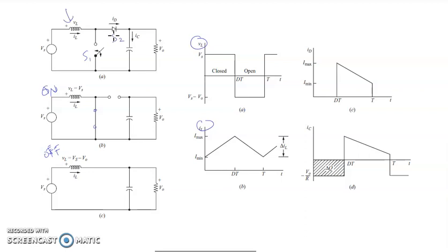It cannot go to the diode and load side, because we have resistance there. It prefers the zero resistance, which is the switch, a short circuit, and returns back to the source. So you can see that the voltage across L, VL, is equal to V source.